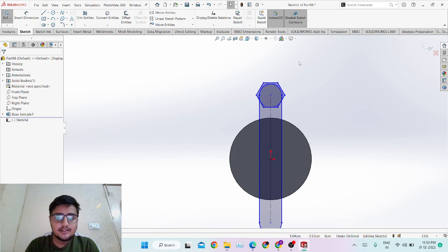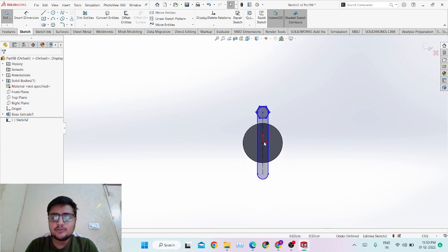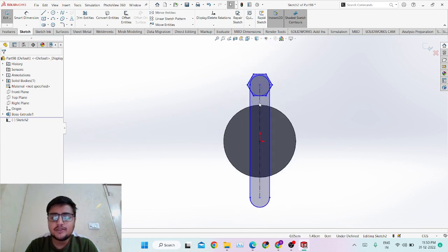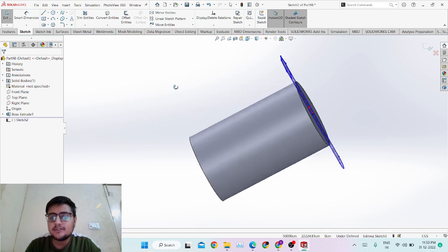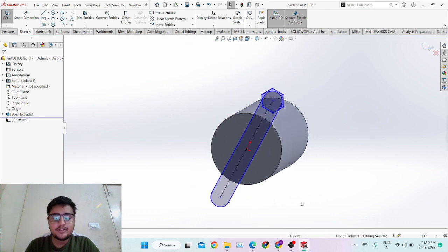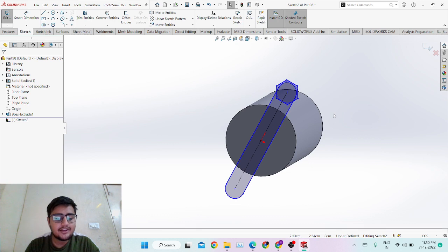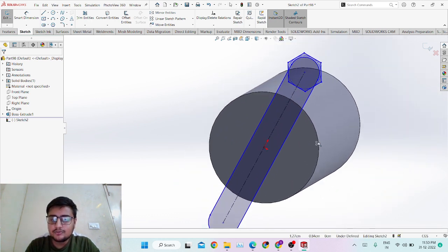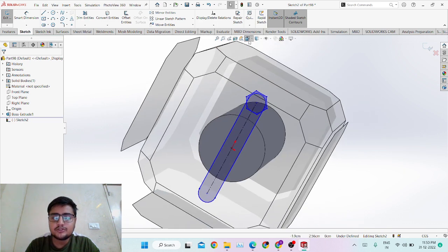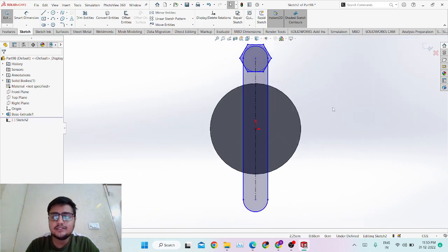By the left key you can click on the objects and everything, and by the scroll you can zoom in and zoom out. You can rotate the model by pressing the scroll key. This way it will rotate. And if you press Control and the scroll key, this way you can slide. Shift and the scroll key, you can zoom in, zoom out. Or if you want to go into some reference place, you can go in like this.